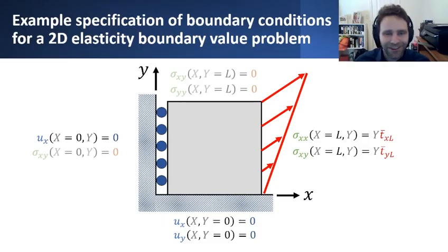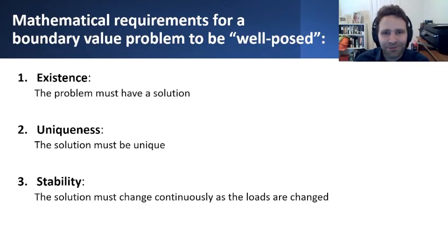It has all the ingredients we need to be able to uniquely solve for what the resulting displacement field would be for this block under these applied loads and with these prescribed constraints or displacement boundary conditions at its various edges. Now, that's not true of all boundary value problems. Not all boundary value problems are created equal, unfortunately. Some are well posed and some are not well posed.